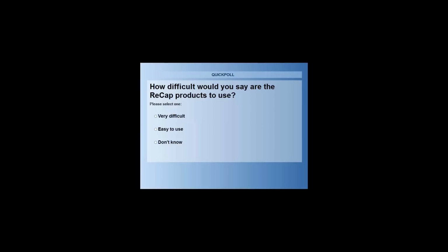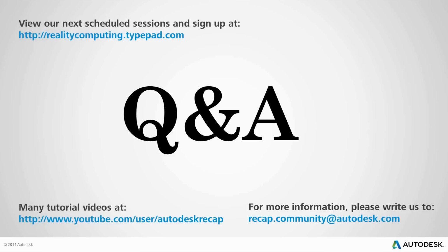Okay. We have a question coming from Michael, and he's asking, what percentage is acceptable for balance overlap points when registering in ReCap Pro? Yeah, so I'd say that the most important metric is your quality metric, so how much of your overlap region is aligned well with the data that's already in there.